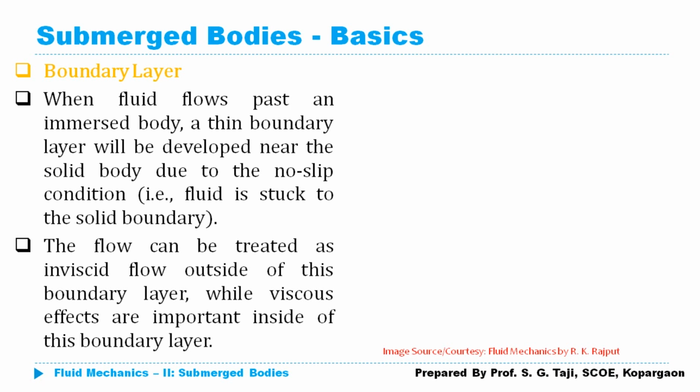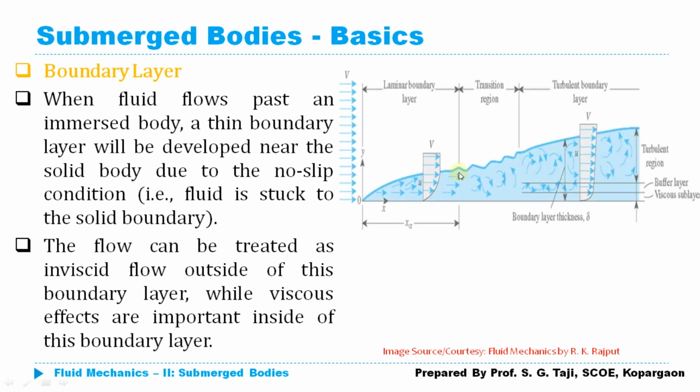Next basic is the boundary layer. So we all know, whenever my fluid comes in contact with a solid boundary, or whenever any object or obstruction comes in the flowing fluid, at that time there will be a development of a boundary layer exactly near the boundary, due to the no slip condition because of the adhesive forces of the liquid.